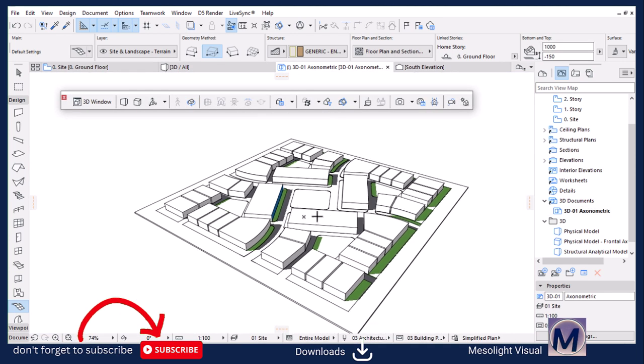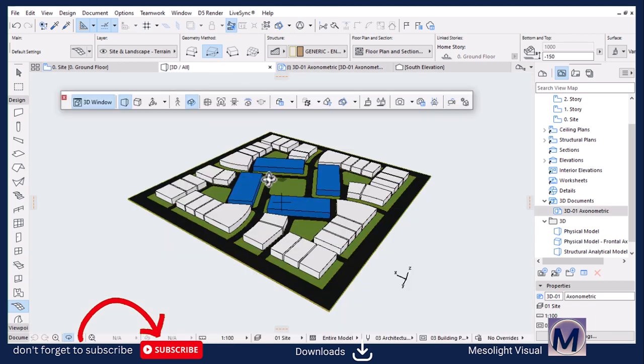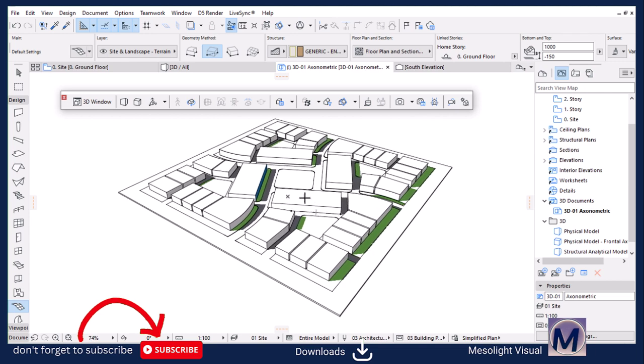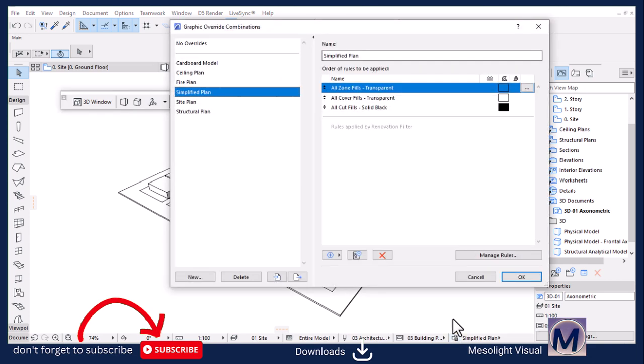All right, so what we need to do here is to highlight or differentiate, as you can see on the 3D here, there's a contrast between residential and commercial. We want to consistently have it on our 3D document. So I'm going to use layer graphic override combinations. We have the simplified plane graphic override combination we used here. We're going to edit or modify it. So I'm going to click on this tab to open the graphic override combinations setup.